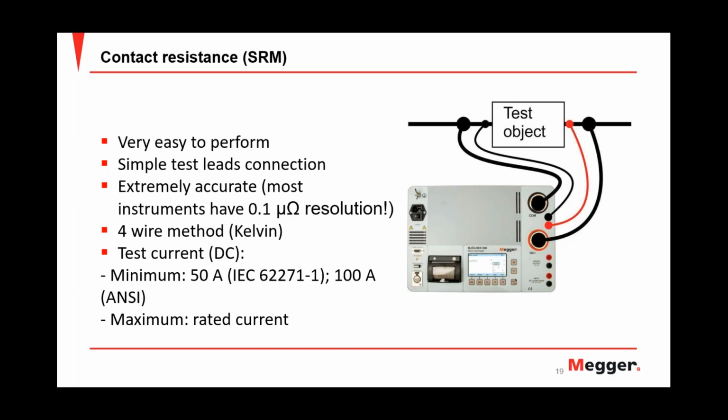It is very common on the market to find power utilities testing with low currents, 10 amps, but the standards lately started to request higher currents to be used. So IEC standards require at least 50 amps to be applied for the test.